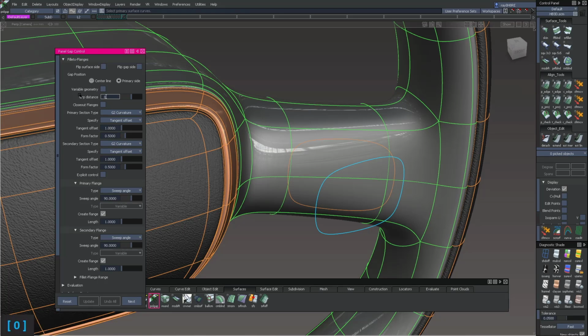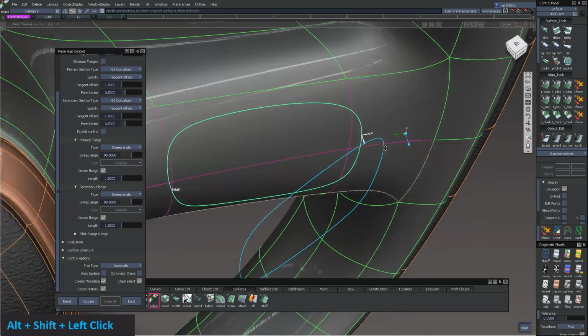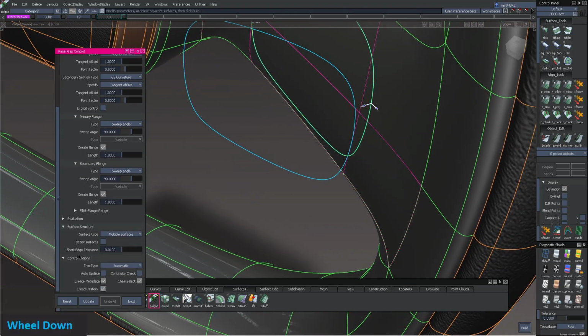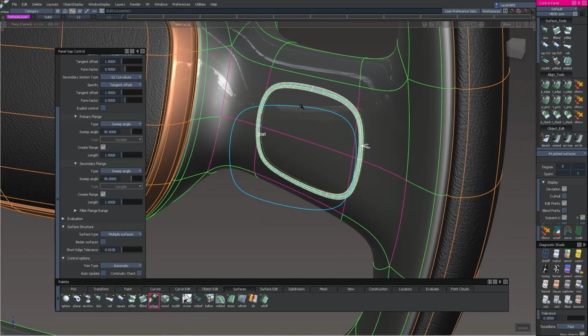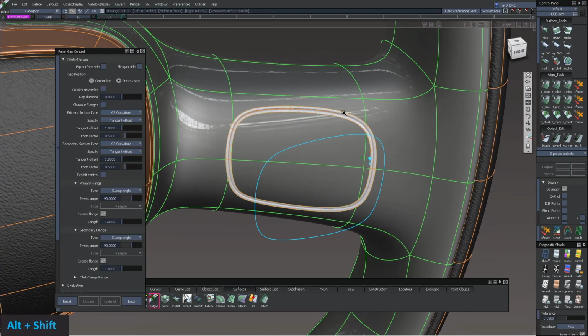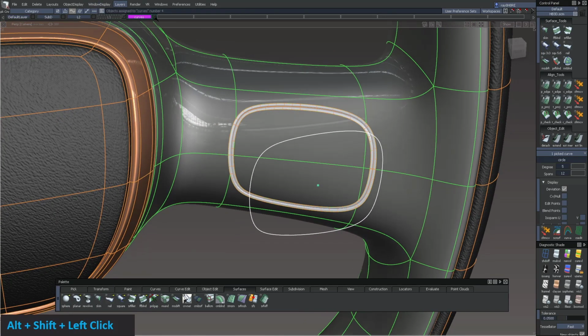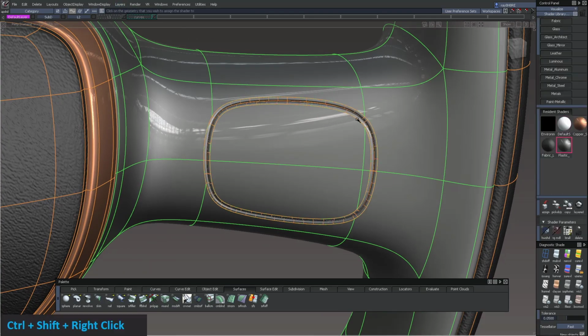And then I'm going to click on chain select so that it selects all of my new curve on surface, which was actually just based off a circle that I squared up a little bit. And then if you see those arrows, I'm going to make sure the arrows are pointing inside and then out. And then once I click enter, it actually gives us this nice little panel gap. The only problem with this tool is that once you're done with it, you're going to have to untrim and divide and then regroup just to change it to two different parts. But it's a very powerful tool.